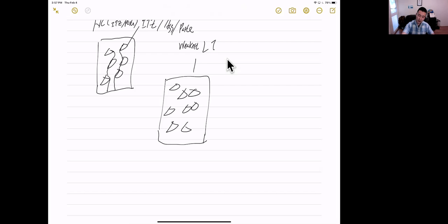So for high strength concrete, HSC, the weakest link may become aggregate. So the crack will go through the aggregate instead, around the cement paste, something like that. So when the weakest link is aggregate, and if we improve the weakest link by using stronger aggregate, then the strength will be higher. Okay, does that make sense?